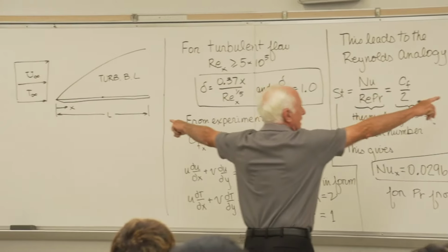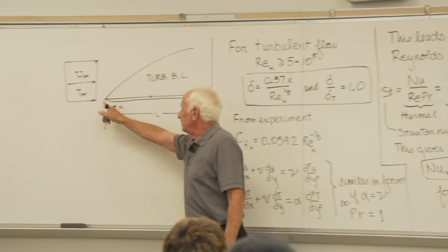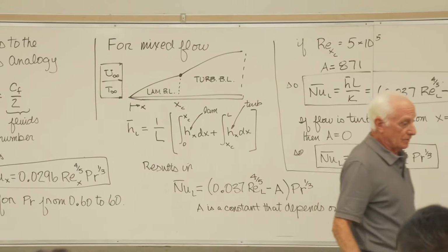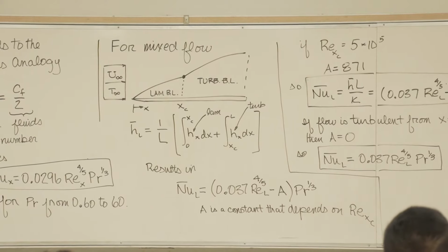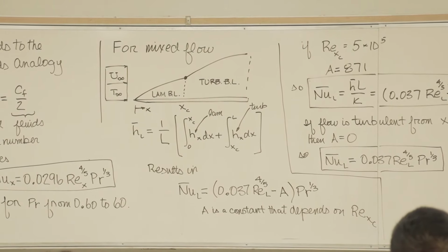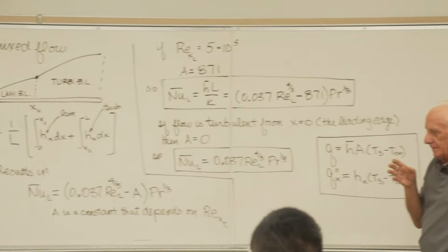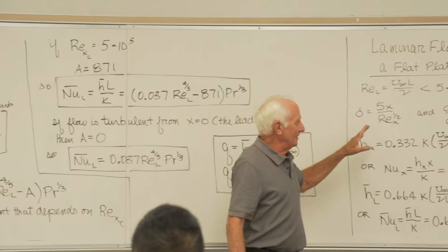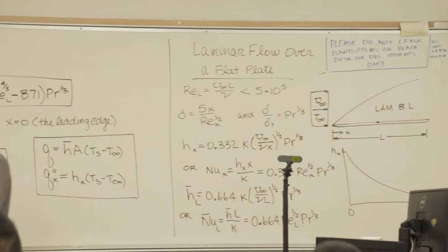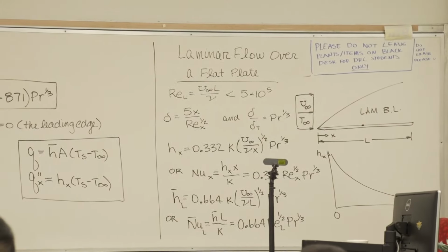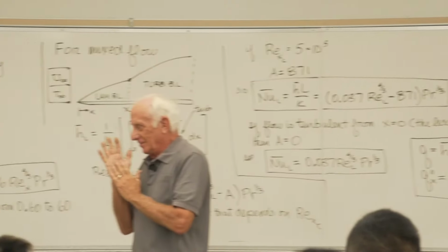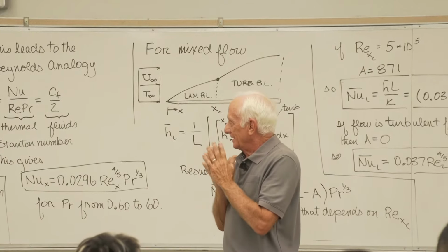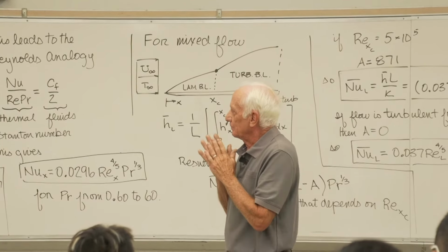What's the difference in these two? How come one starts out turbulent from the leading edge, but the other starts out laminar? Well, you've got to read the words real carefully. You won't find a totally laminar boundary layer a lot in the real world. It's hard to get, because the flow approaching the plate is not always as nice as you'd like it to be.